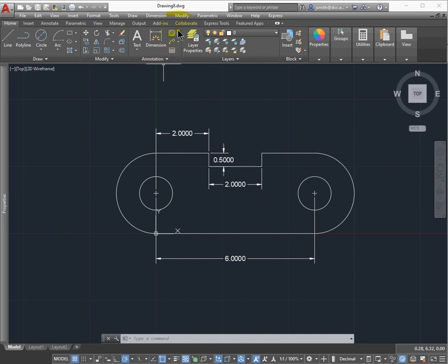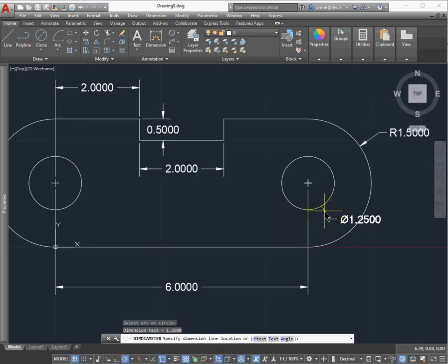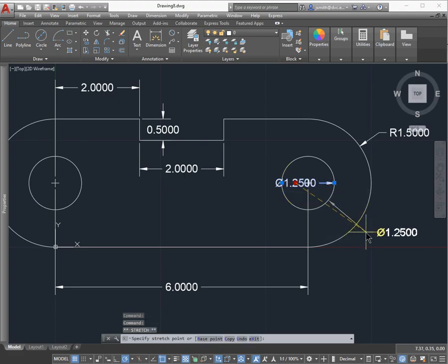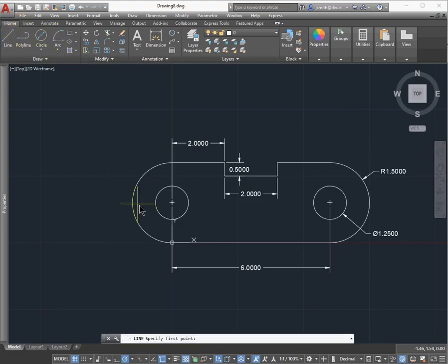All right, and so if you click on the dimension there on the side, there's an arrow, and if you're dimensioning a circle, a full circle, it should be a diameter, but if it's not a full circle, you should always dimension it to be a radius. I actually teach that in the 119 class. We don't really do a lot of teaching how to do dimensioning in this class. We just are following the textbook because it's so many menus here.